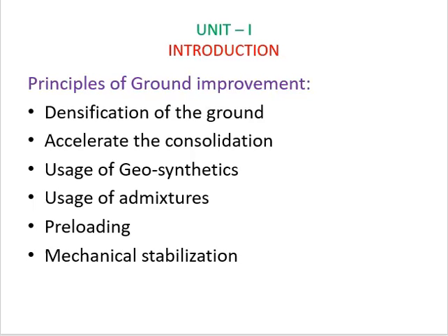Then second principle is accelerate the consolidation. In case of finer soils like clays, the density will be increased when the pore water is extracted from the soil, which is a time-taking process. For such kind of soils, the consolidation process has to be accelerated by using some artificial means.